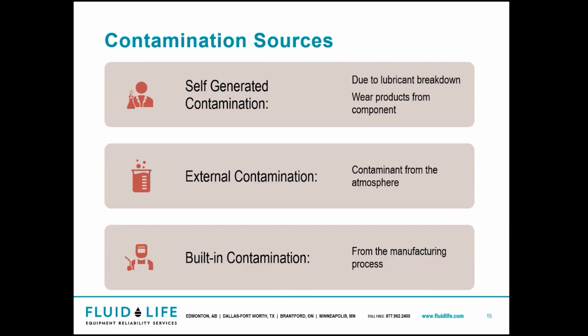So as I mentioned before, you get self-generated contamination, external contamination, and built-in contamination. Just like I mentioned, my colleague with his vehicle contamination, anything that comes in from the air. I mean, you open up a fill cap, you open up that barrel of oil to put in a drum pump, or even the breakdown of the components, because oil is going to break down, whether it's premature from overuse